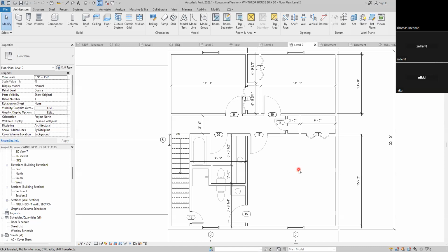So we're going to just start to put those walls in. Okay, we know how to do that. So we're going to start to place the walls, and remember, it's interior to interior. So let's start by putting in, first of all, the 10-foot wall. Okay, this is a 10-foot wall right here. You see it's right here, and this says 10 feet. So this wall goes right here and goes down 10 feet. So we're going to start with that.